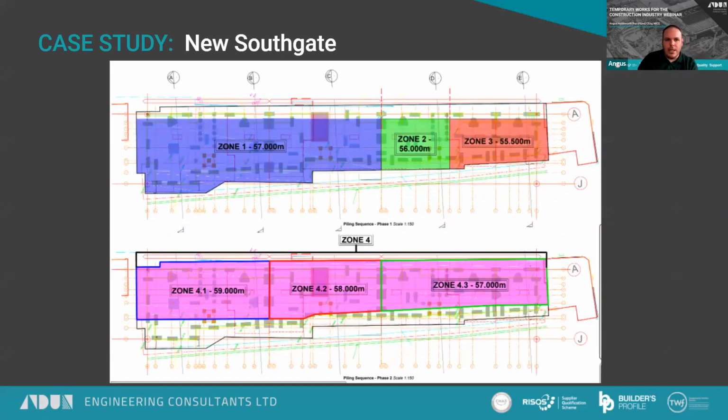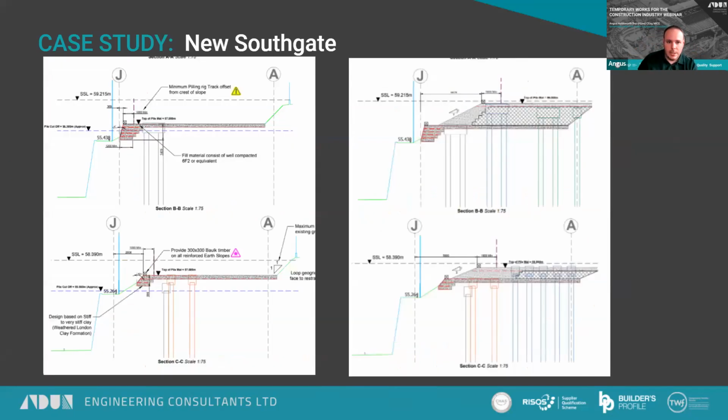So taking all that into account, we went back, solved the problem and came up with a solution. It required taking a lot of fill off, but given the lack of information, the lack of time to go and get any information on the wall, the best solution for the project was to keep moving, even if it required excavating a bit more ground. So we utilised the removed soil to justify the surcharge that we were applying behind the wall. The logic being, it's currently supporting that load at the moment. If we take that surcharge off, we can replace it with plant loads.